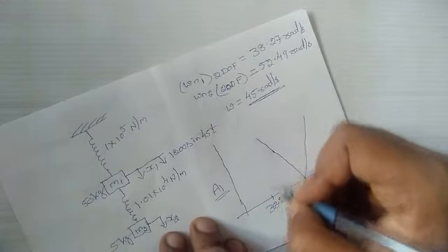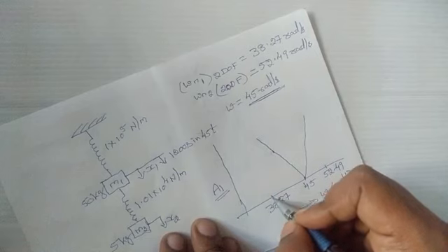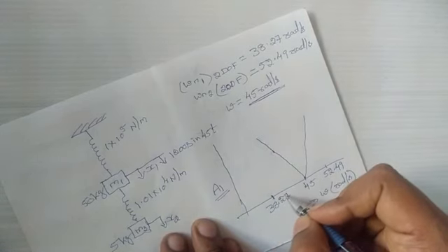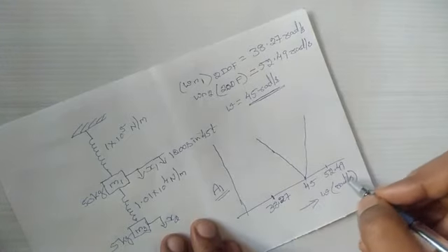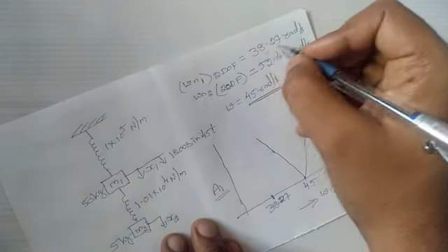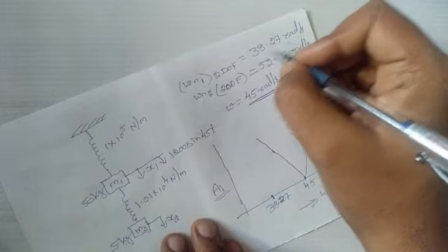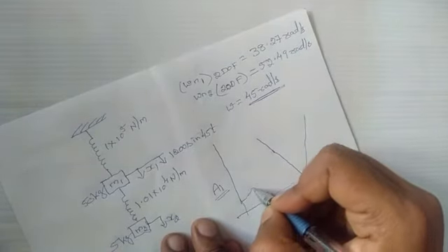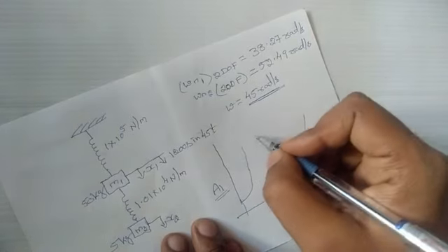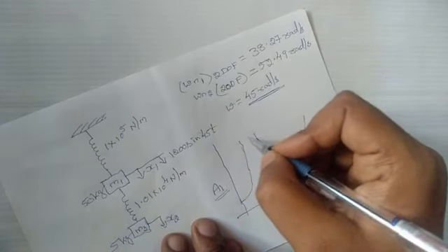Okay. So how much is the amplitude going to be at 38.27 radians per second? Because this is the forced frequency and that is equal to the first natural frequency of this 2 degrees of freedom system, the amplitude of vibration is going to be infinity.